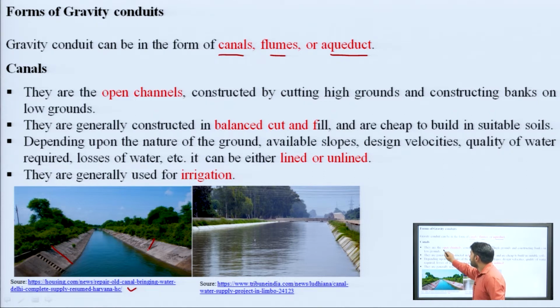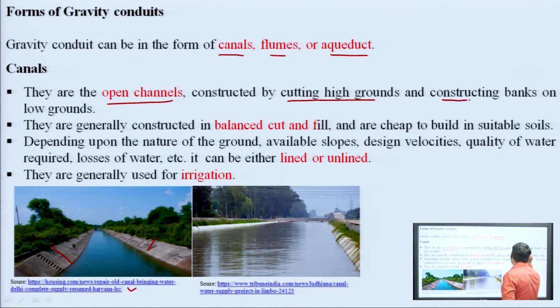So, canals are open channels constructed by cutting a high ground and constructing banks on the low ground. There will be two possibilities: if the ground is at a certain height, then we have to cut that particular ground, and if the ground is at a very low level, then we have to fill it, means we have to perform both cutting as well as filling.